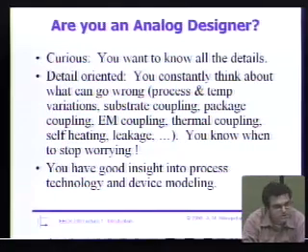Unfortunately, a lot of these unpleasant things aren't really in the model, right? So substrate coupling is not in your model, right? You can try to do substrate coupling analysis with tools that try to do it for you, but it's very painful and very slow. Package coupling: most of you don't simulate your circuit in the real package that it's actually going to end up in, or in the real environment in which it's going to reside, right? Do you know what chips are going to be around it? Do you know what coupling is going to come into it? Well, you should. You should think about these things, because these kinds of issues could end up being a killer. They might make your product unusable.